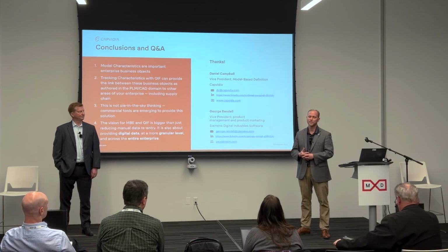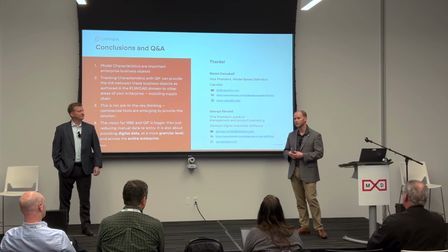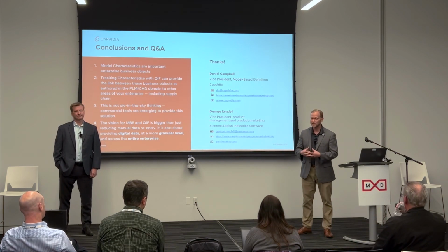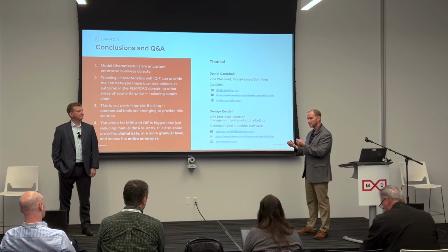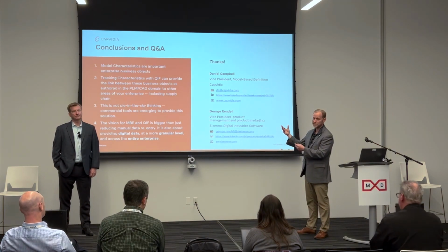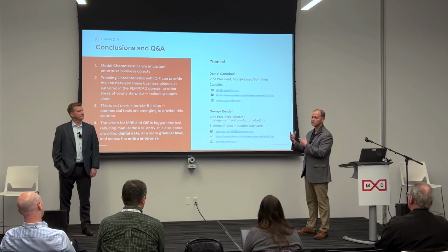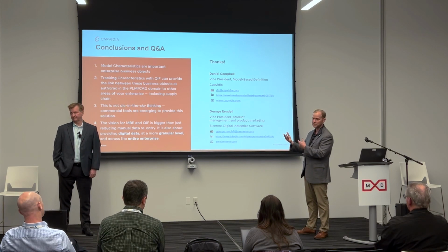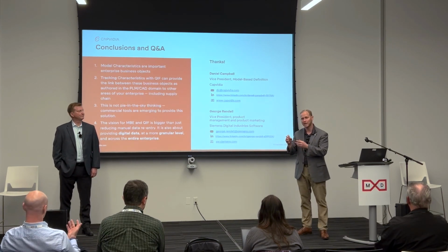there's a third-party online QMS system that you're familiar with called NetInspect. We can take the bill of characteristics from NX and publish it to NetInspect. The supplier can view that on NetInspect, do their work like they normally do, and enter measurement results data up to NetInspect, and then we, on the Capvidia side, can pull that data back down from NetInspect.